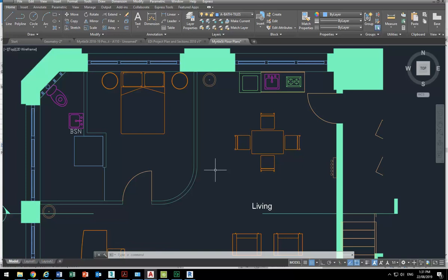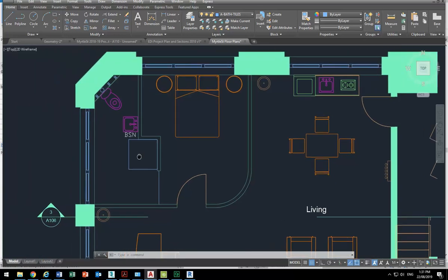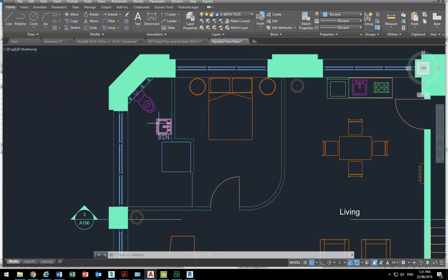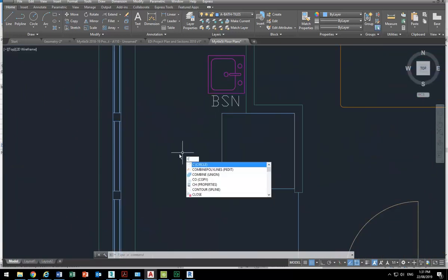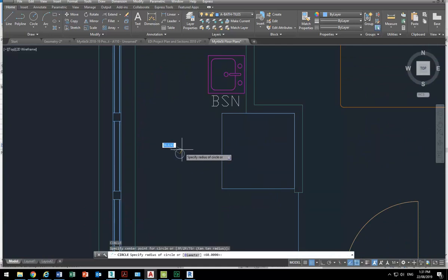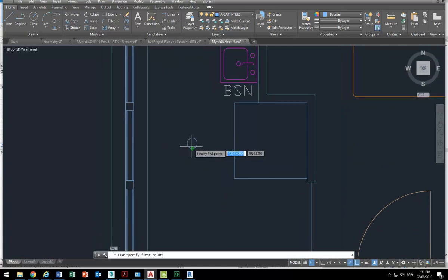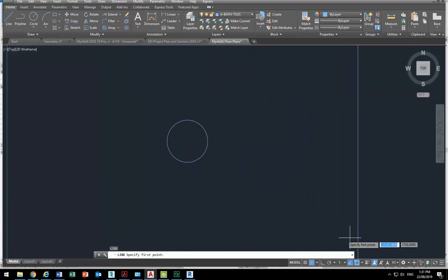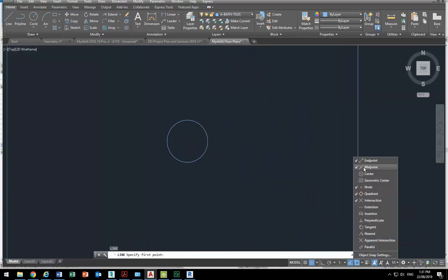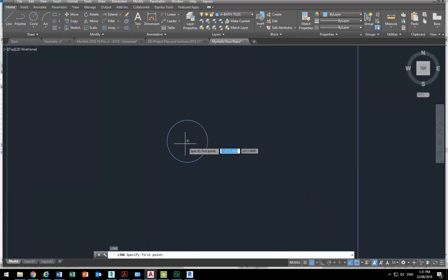Yes, floor waste. Good point. Absolutely, floor waste. So you can start to put in floor waste. The symbol for floor waste, we're over time, but anyhow. The symbol for floor waste is just a circle with a cross. So I'll just get the centre turned on. Should we insert the symbol, not draw them? There's a symbol for this you can find, but it's such an easy one to draw. I'll just draw it because it's just this. We know how.